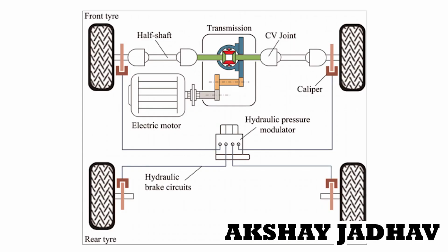The working of the Motor Generator Unit Kinetic is that it converts mechanical and heat energy into electrical energy. So the MGU-K is an electric motor connected to the crankshaft and helps turn the crankshaft, therefore producing more power. The MGU-K is directly connected to the rear wheels. It returns up to 160 bhp of power to the drivetrain.